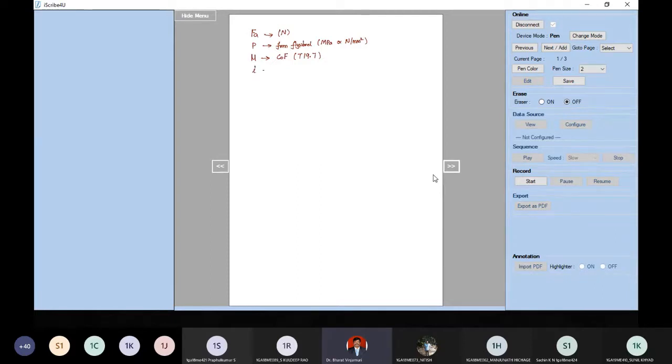Here there is one more factor, i, the number of active pairs, or frictional plates. I'll try to explain it; this is not an issue. So mu and i you have done. Then what else do you need? You have D1, the internal diameter, and D2, the external diameter.